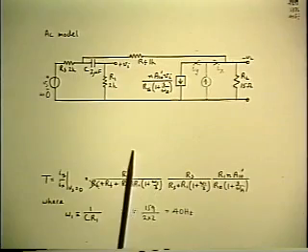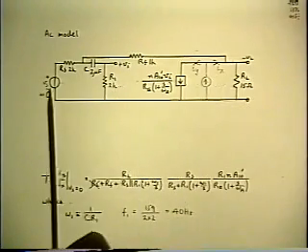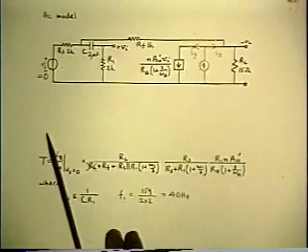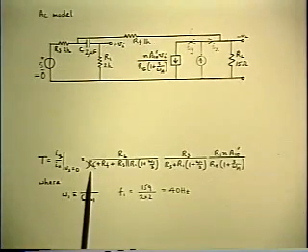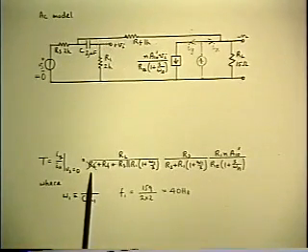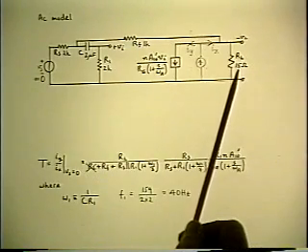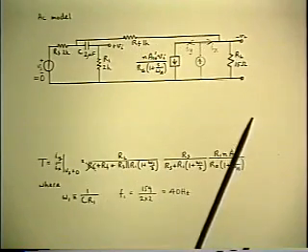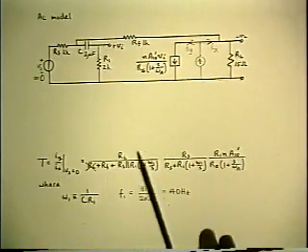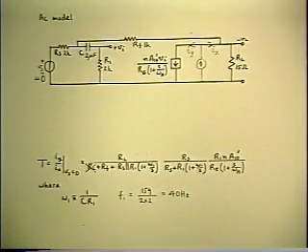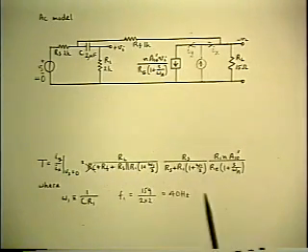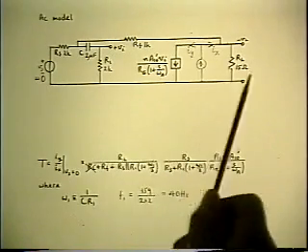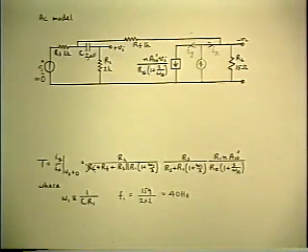The very first line when we wrote down the loop gain by injection of the IZ. There it is. Dropped the RL. For the very good reason that RL is 15 ohms compared to RF, which is 1K. And I mentioned at the time, that's a very good approximation. And even though we're sticking our necks out by saying that we may want to change values later, it's not likely that we're going to invalidate that approximation.